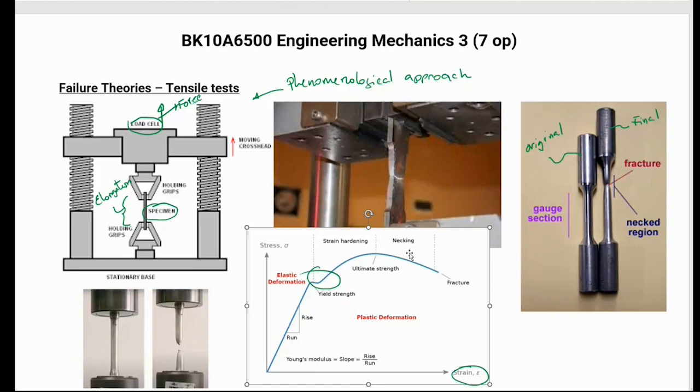So you see that here you have a material that evidently behaves according to Hooke's law. You're going to have the straight section of the curve, meaning that there is a proportional response between the force applied to the part and the elongation that the part is going to have. So this is the proportional part. And in this proportional part, as you know, this is the elastic deformation.